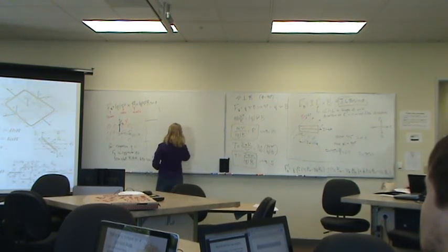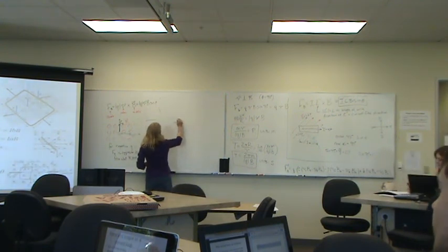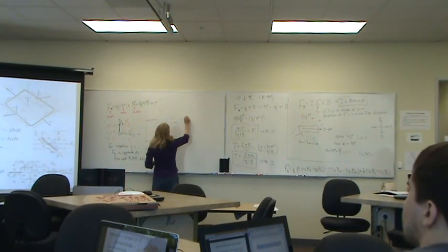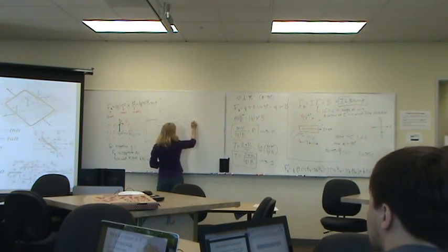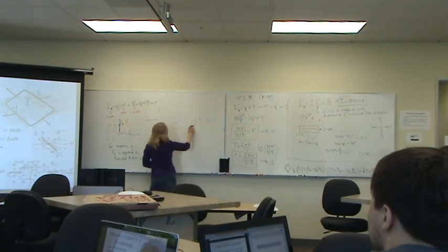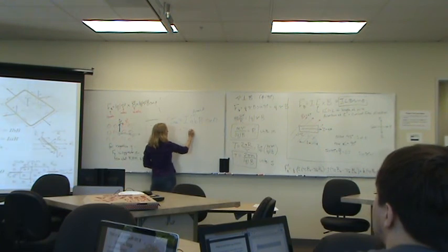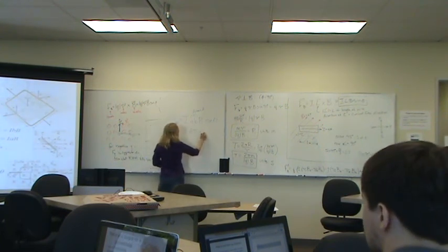So the take-home equation is that the net torque on that loop would be I little a little b times the B field, and then sine theta, where the angle is changing as it rotates. For that square loop, little a times little b was equal to the area, so you can write that as I, big A, big B, sine theta.